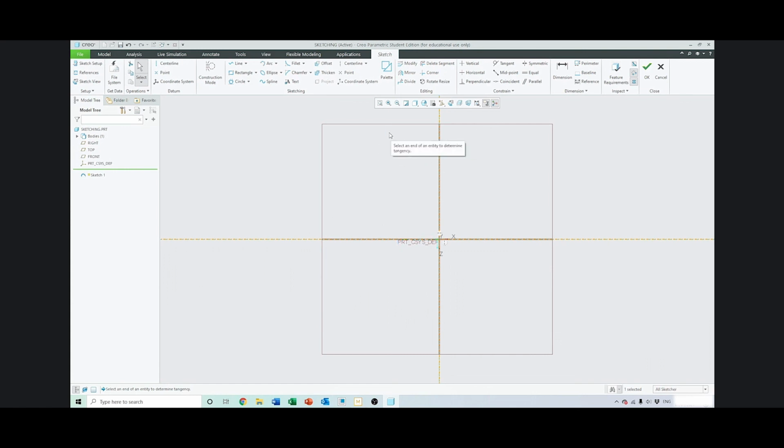Okay, let's do the next one. Here we have the center and ends. So with the center and ends arc tool, first of all you need to choose the center, and this would be the center of that arc or that circle. I'm going to click that into the center of our axis, and now you see that a dotted line is formed that shows you the diameter of the potential circle / arc you're going to be making. The first time you click will be the start of that arc, and then you can see the arc being created from that first point around the edge of that circle. Click again to finish the arc, and then again you can dimension this however you wish. I'm just using Ctrl Z to delete this to move on.